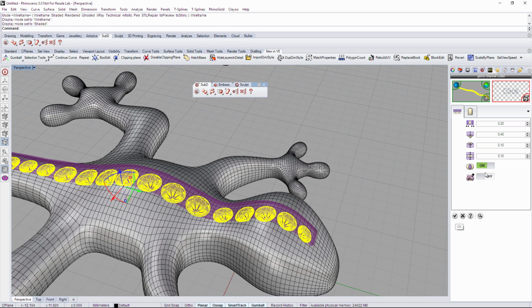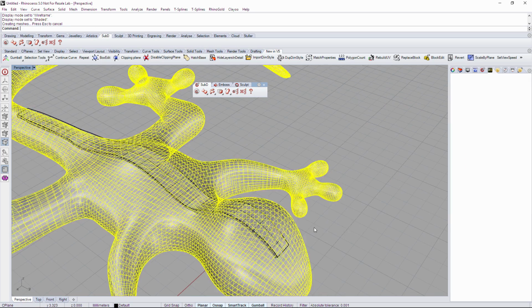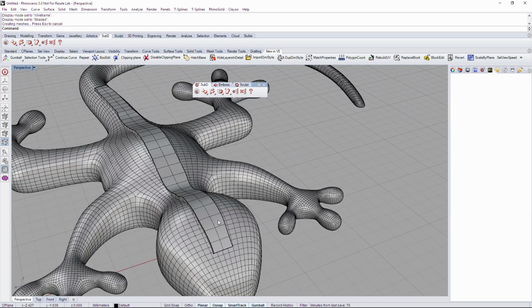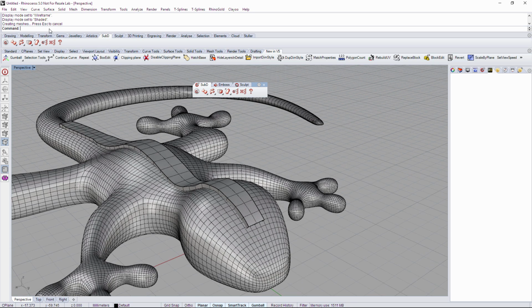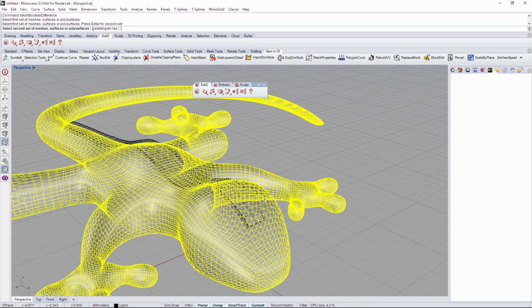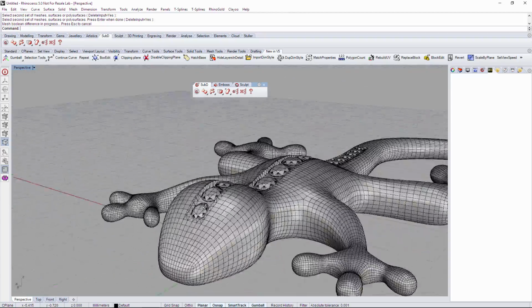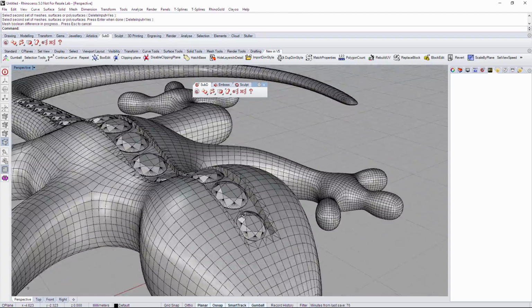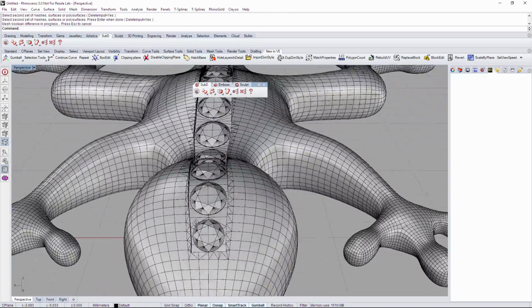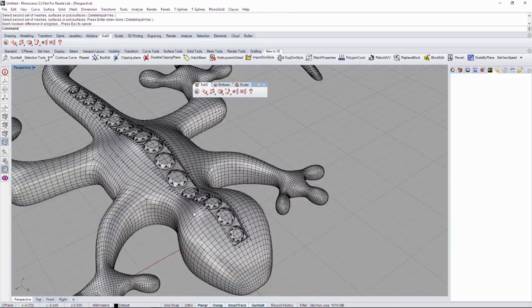Okay, and maybe I'm going to create a copy for the object, and I make the boolean later. Okay, so I'm going to validate, and in here I have the channel cutter and my object. Okay, so I'm going to go to mesh boolean difference, so from the lizard and the cutter. Okay, and there we go, the gems with the cutter. So now we only have to apply the prongs on the gems.